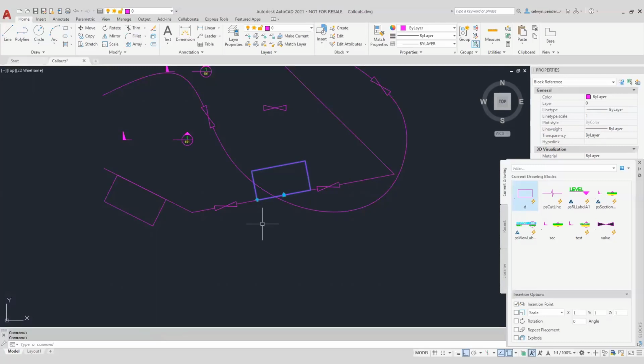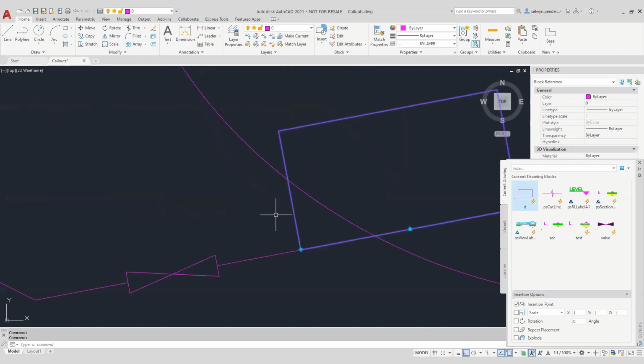Just one quick question, Selwyn. Yes. Leon's asked whether or not we can override any of the parameters when we're inserting a block, and I suppose it's similar with attributes, whether you can override any of those preset items. No, the preset items will come in as they are. The only way to overwrite them is to actually modify your block, depending upon what your action is trying to do. If you don't want the flip to be in action, just don't use the flip. You've got the option of using the additional grips in there, but they're not compulsory.